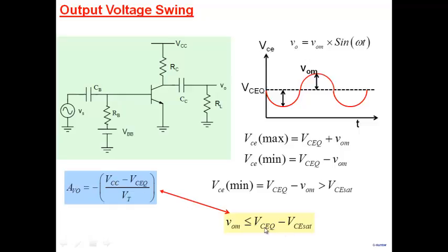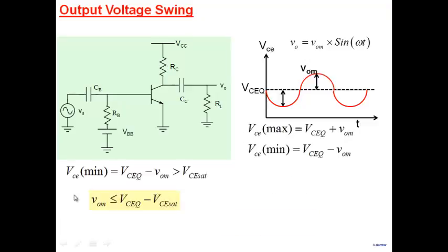If you want a higher swing, say I make it 2.2 here, then 2.2 minus 0.2 will give me a 2 volt swing. But then when I put 2 here, the gain will fall. So you can see that all these quantities, whether you look at gain, input, or output resistance, depend on a handful of parameters: RC, VCC, RB. So if you try to influence one quantity, the other quantity also gets affected, and usually in a wrong manner. If you try to increase VCQ to get high swing, the gain also falls down. All right, so this is the picture that we have then.